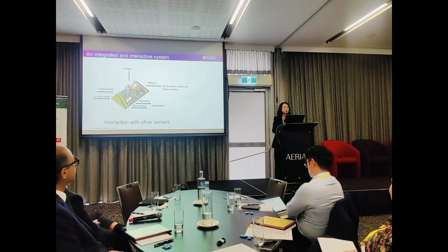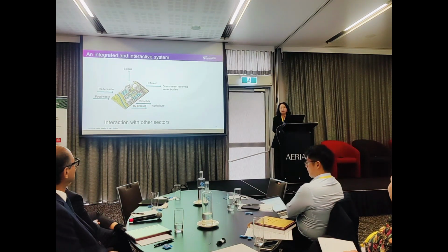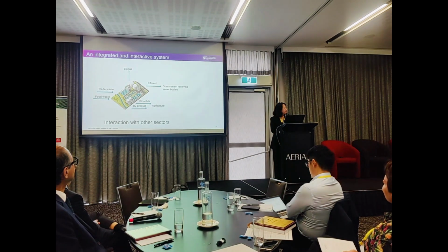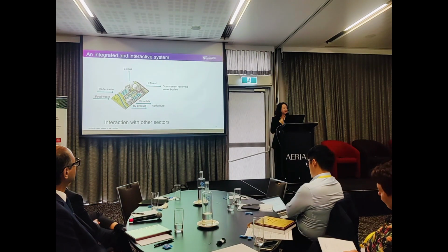However, we also need to be careful that when we take out the carbon from everything we take into the system, with the leftover digested liquor, the nitrogen stream, we have to look after how we can remove that in our existing treatment plant. As mentioned, if too much nitrogen comes in and we have already taken the carbon from it, we will also suffer from later N2O emissions.